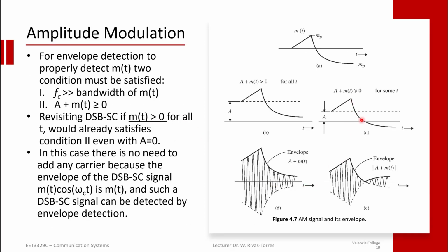So in the case when you cross zero, notice what the envelope looks like now. For a portion of the time, the envelope does look like our signal, but then it doesn't, because our signal, after the peak, is monotonically decreasing all the time. But notice here that all of a sudden it starts to increase. So this would be a distortion for us.